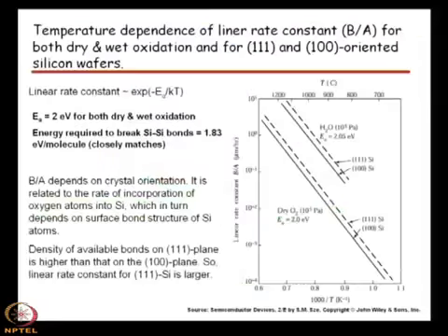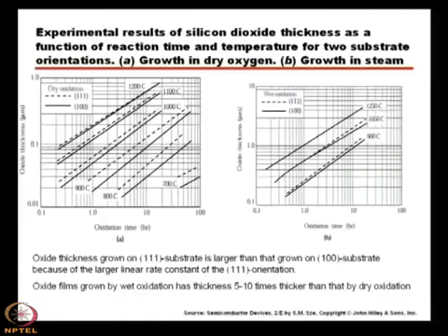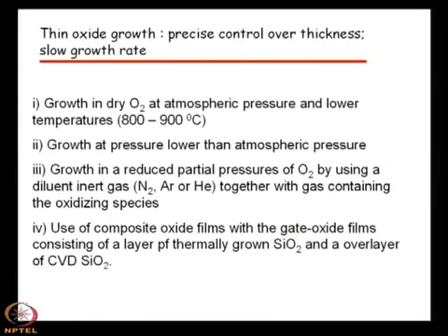oxidation, this is thermal oxidation, because we shall come across other oxidations also, like the CVD of silicon or other types of oxidation, and we shall find that there are other applications also, not only for making the gate oxide, but in some cases for isolation, or for making the mask for the diffusion or lithographic pattern.